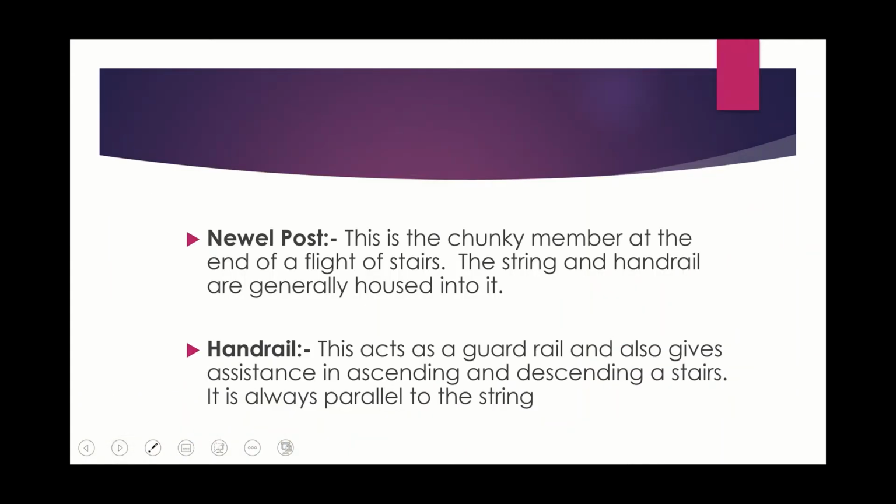The newel post, this is the chunky member at the end of a flight of stairs. The string and handrail are generally housed into it. The handrail, this acts as a guardrail and also gives assistance in ascending and descending a stairs. It is always parallel to the string. Diagrams will help us understand these. I'm sure people know what we're talking about here.